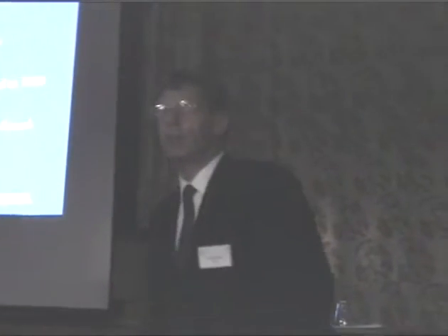Sasol has looked at the operating procedure of those reactors. They have further refined it to the extent now that the reactors that you will see at Sasol, the 3 of them, well, if you go down there, have an online availability of more than 99%. That's an extremely high online availability. So one can successfully operate circulating fluidized bed reactors for Fischer-Tropsch applications.